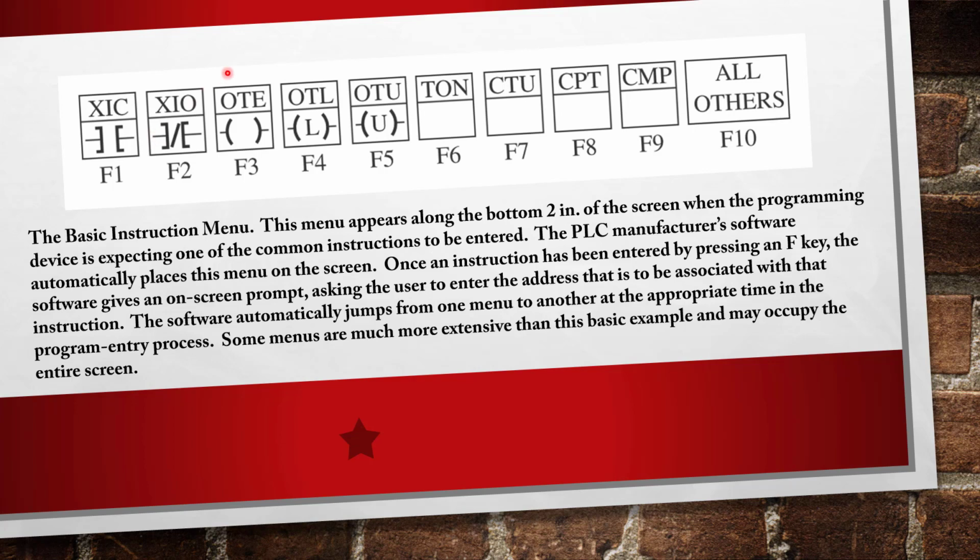So when I have my logic that's just software based, I can change all the connections internally, and everything's still hooked up on the outside as far as my inputs and outputs. If I want them to do different things, I can make those changes in the software with drag, drop, delete, copy, paste, whatever, and I never have to remove a wire from any relay or contacts.